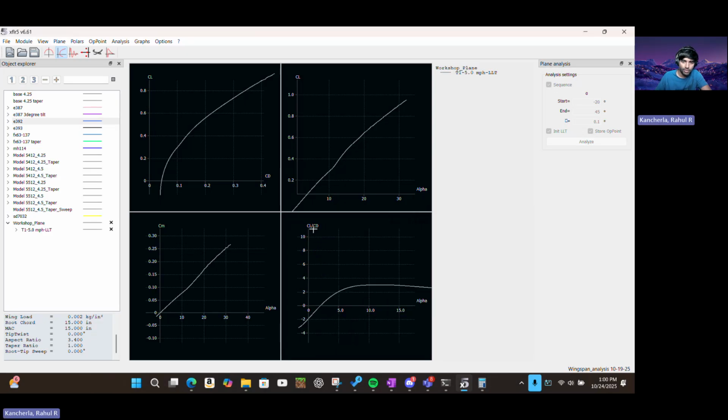And then the ratio of lift to drag against alpha, which is the angle of attack. It's pretty stable. It gently decreases as the angle of attack increases, which is typical. Stability decreases as you try to ascend and experience more turbulence.